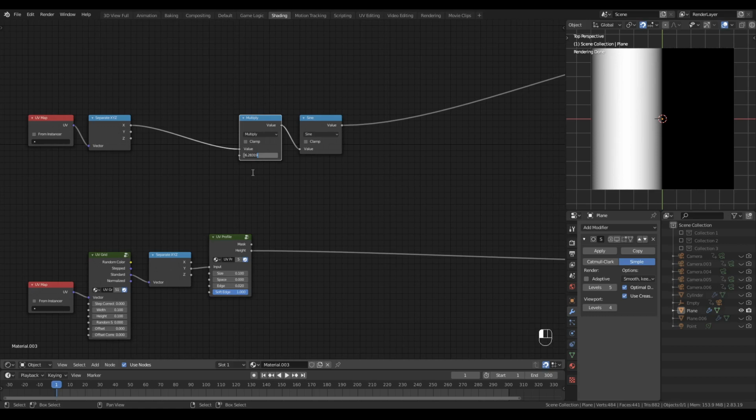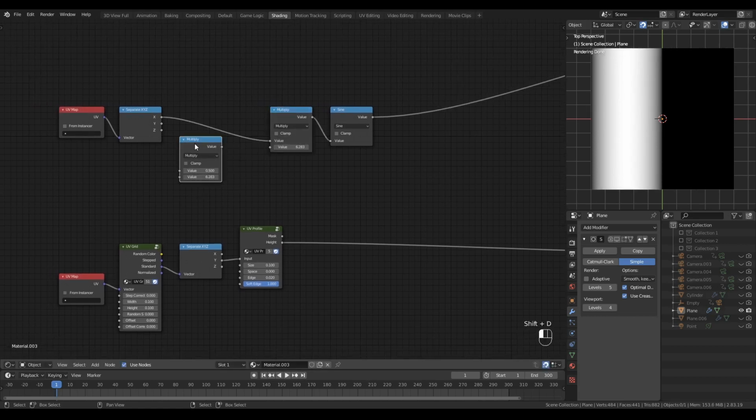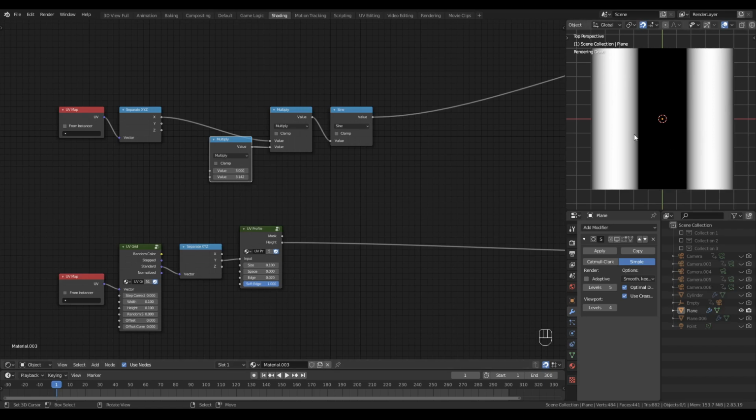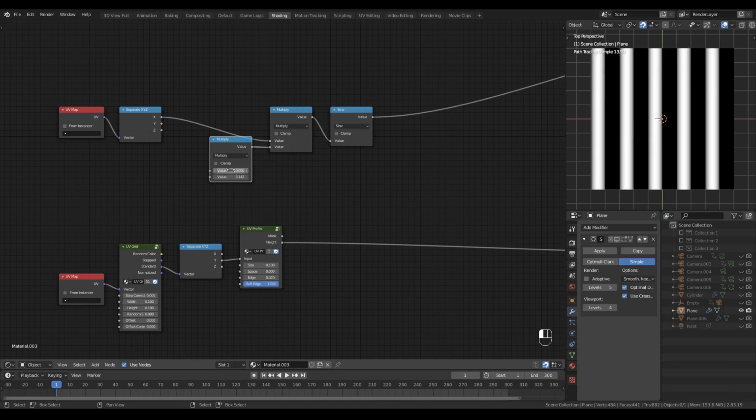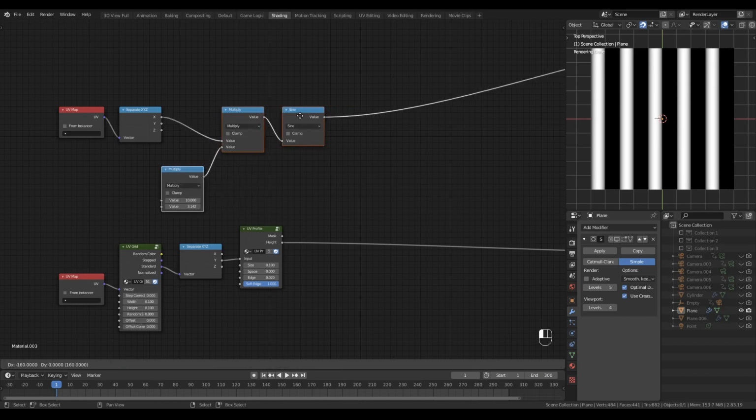by giving the sine node the value of pi multiplied by 2. So I can use a multiply node with an integer value in the top, 2 for example, and pi in the bottom, plugged into the bottom of this multiply node, and now I can choose how many peaks and troughs, how many instances I get in any 0 to 1 gradient or UV map by increasing this integer right here. For now I have 2, meaning 1 peak, 1 trough. If I go up to 3, 1 peak, 1 trough, 1 peak, etc. You can see how this works. If I set that to 10, that gives me 5 peaks, 5 troughs, or 10 instances, as I'll call them, to avoid repeating peak and trough over and over.